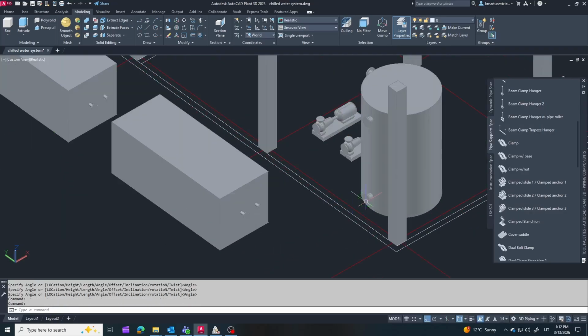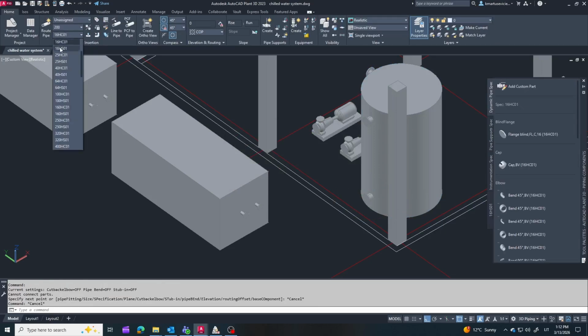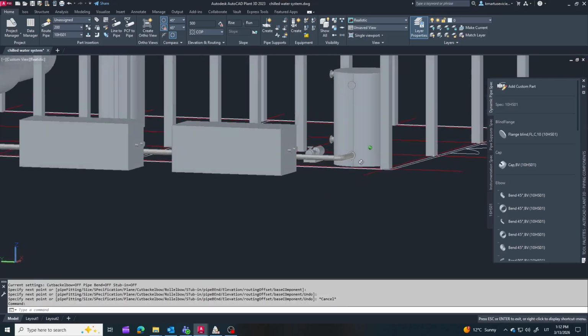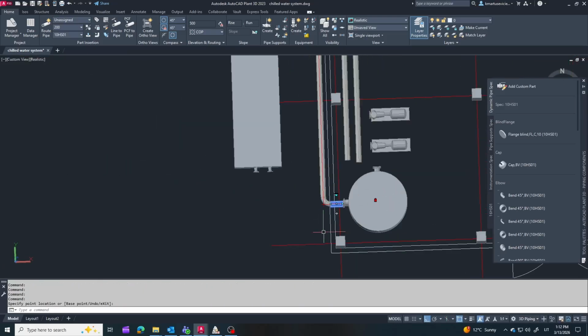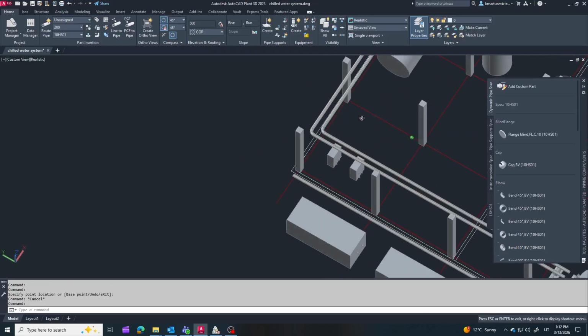I already started creating the nozzles on the tank. They are the same size as before, DN200, just rotated toward the chiller side. This position should work well for connecting the chiller loop piping. Now I create a simple loop for the chillers. I think I will adjust the nozzle heights on the tank slightly to improve the water flow pattern.